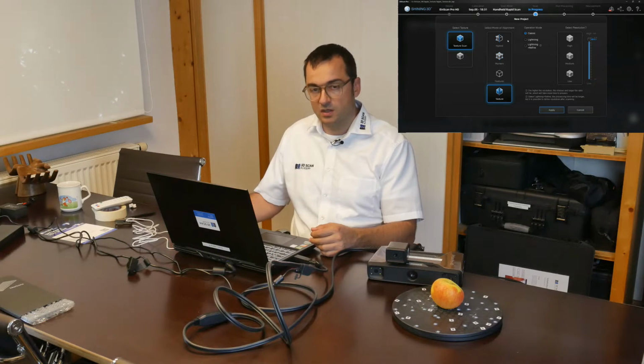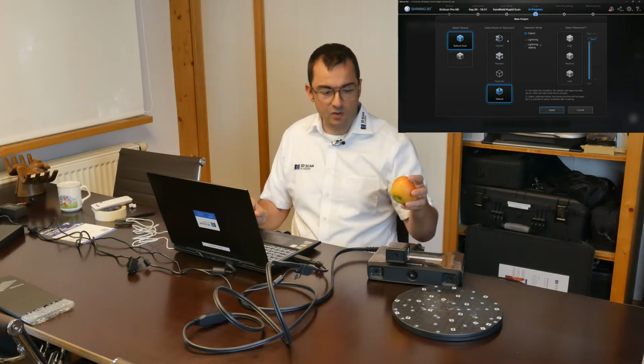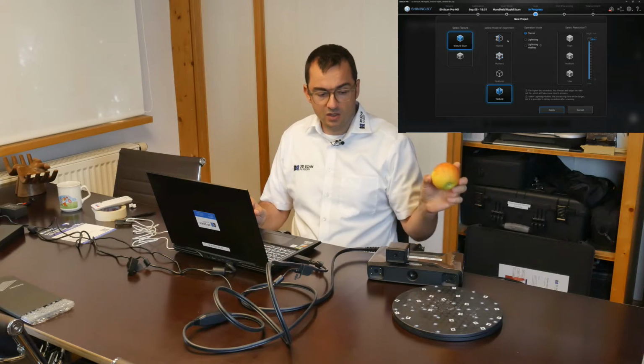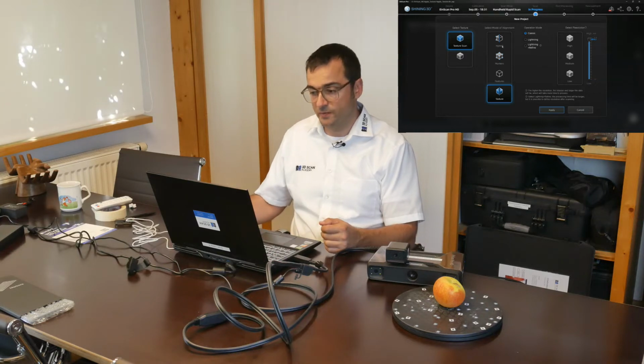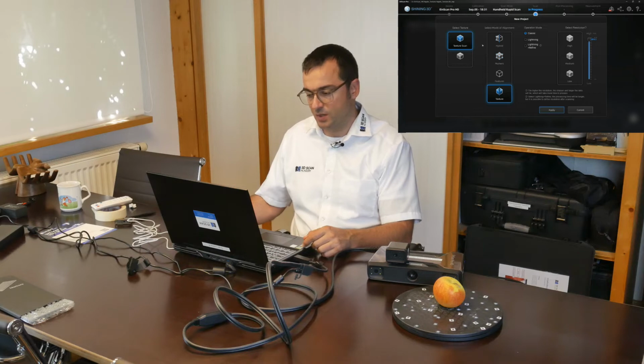If you would imagine that same globe just in glossy white, and looking at it, it would be rather hard to know if you're upside or downside on that globe, because it will look all the same from all the perspectives. And that would happen to the scanner as well. He would look at this globe, and that all white globe for him would look the same in each kind of the orientations. So using the texture on it, that means in this case colors, letters, whatever is on there, makes him able to orientate himself on the object. And that's just possible in the rapid scan mode.